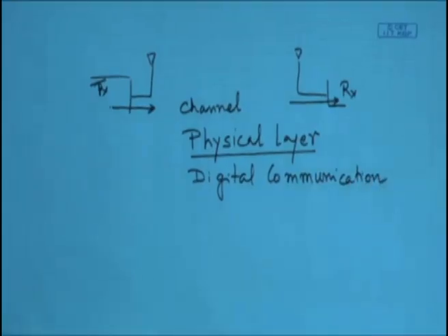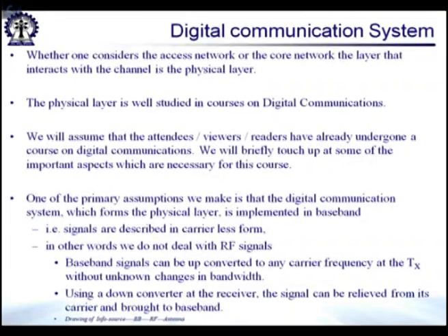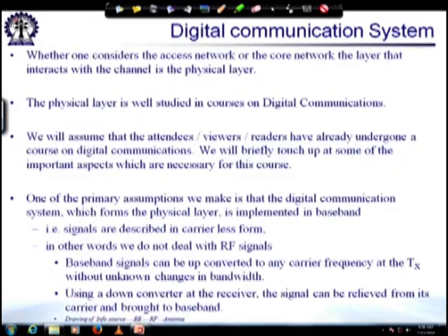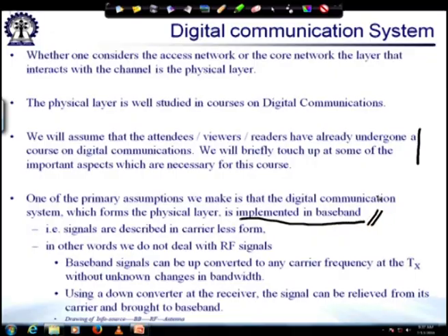We will assume that the students or the attendees of this particular lecture, this particular course, have already undergone a course on digital communications, without which it might be difficult to understand the details of this subject. Now, one of the primary assumptions we make in digital communications is that the signals which form the part of the physical layer is implemented in baseband. Now, this is a very important thing which we usually study in digital communications. That means the signals are in carrierless form. That means there is no carrier representation in the signal.